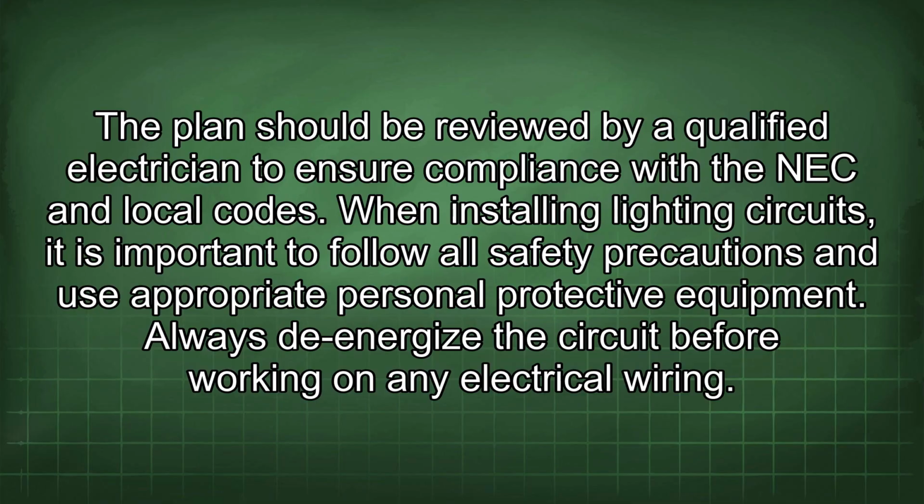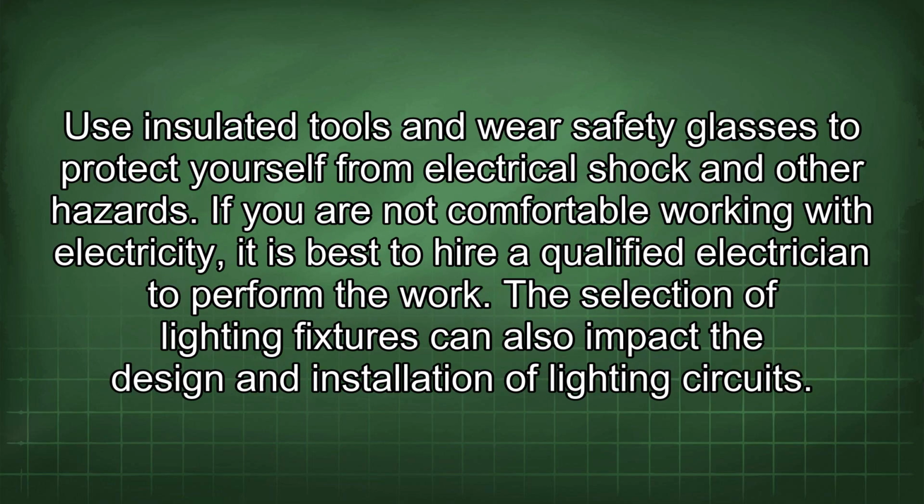When installing lighting circuits, it is important to follow all safety precautions and use appropriate personal protective equipment. Always de-energize the circuit before working on any electrical wiring. Use insulated tools and wear safety glasses to protect yourself from electrical shock and other hazards. If you are not comfortable working with electricity, it is best to hire a qualified electrician to perform the work.